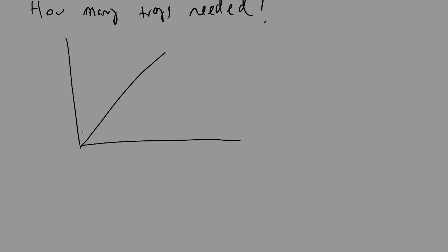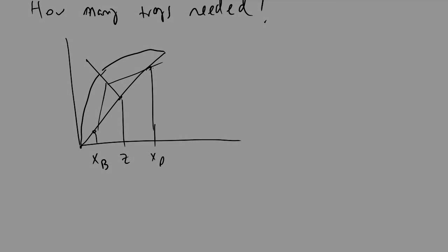So we'll have a diagonal, we'll have our equilibrium curve, we will have our coordinates corresponding to the bottoms stream, the feed composition, and the distillate composition, and we will have our 3 lines that will look something like this. The way we will evaluate how many trays are needed is by stepping up the McCabe Thiele diagram like so.